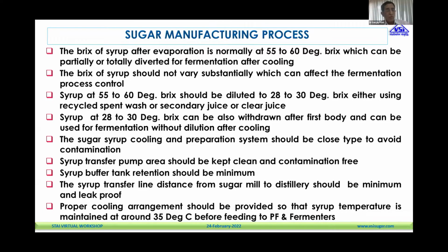One can use also syrup at about 28 to 30 brix. So we can withdraw it after the first body and can be used for fermentation without any dilution and after cooling. But of course, as mentioned by Professor Naren Mohan, in this case, you will have to see the vapor balancing of the evaporator station.